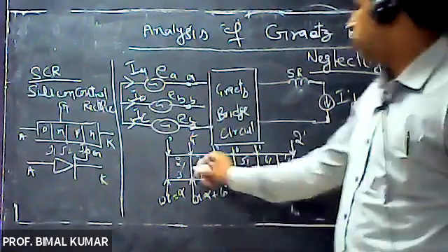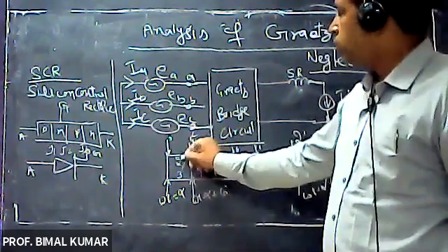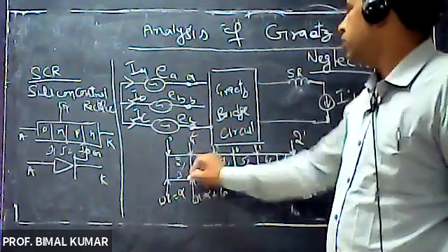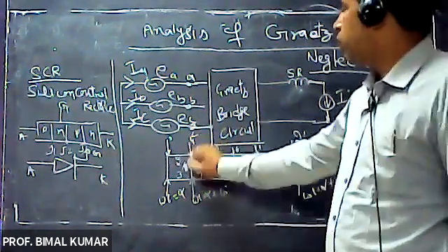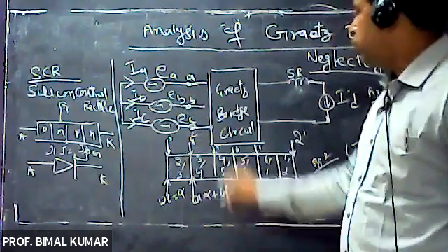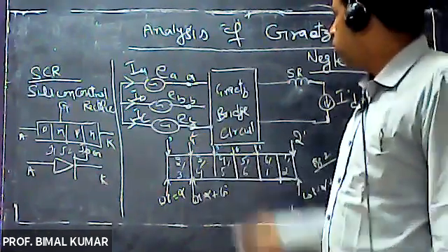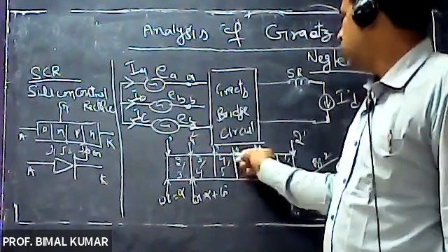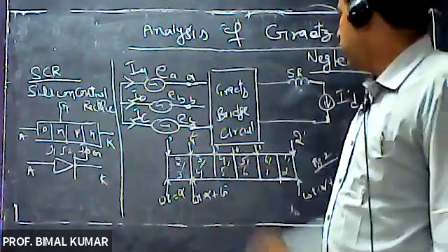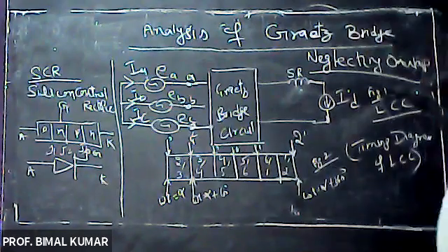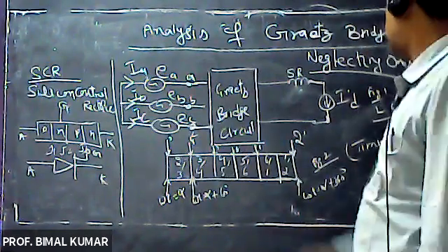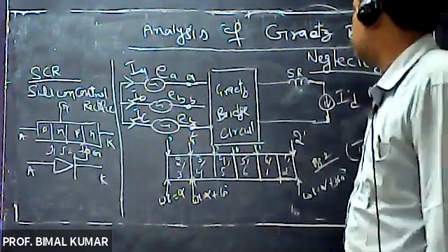During the first interval, switches 2 and 3 will conduct. During the second interval, 3 and 4 will conduct. During the third interval, 4 and 5 will conduct, and next 5, 6, then 6, 1 and 1, 2.